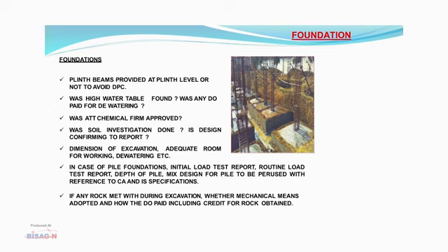The dimensions of excavation and adequate room for working space and subsequent dewatering, if required, has to be catered for prior to commencement of the foundation. In case of pile foundations, the initial load test report, the routine load test report, depth of pile, and mix design for pile have to be pursued with reference to the contract agreement and its specifications.